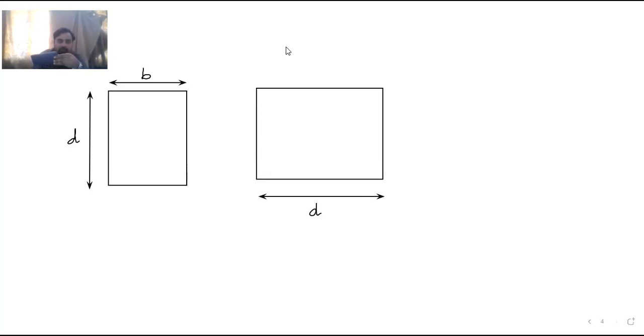But in the case of pre-stressed beams, to transfer the pre-stressing force evenly, we connect one anchor plate here, not on the entire depth, only up to some depth.